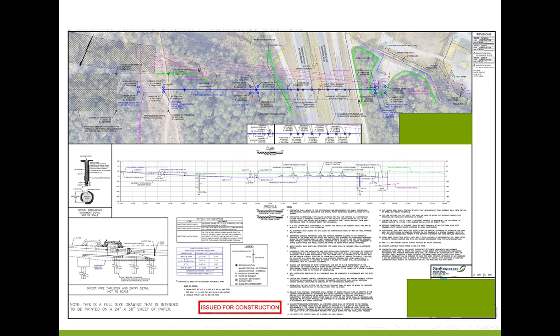From the intermediate vault, the pipe slopes at a constant 0.5% back to the other side, the east side of the crossing. This was an industrial owner, and that pipe, a steam pipe, needed to be able to drain to that interior vault when they were doing maintenance.